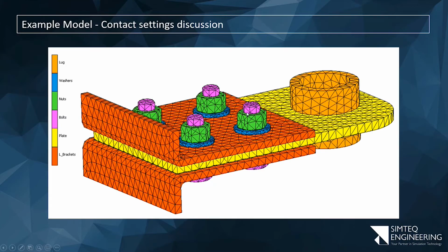But again, I'll use project stress free because I don't want a radial stress between the bolt and the nut. And I want it perfectly in contact. So what I'll do is I'll run the analysis without even a load case with that contact table and check that it makes contact nicely.